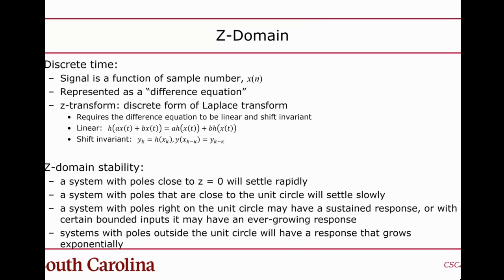The shift invariant and linear properties are just analogs really. Linear is linear, and this means the same thing as it does in continuous. But shift invariant versus time invariant just means that you can shift the time, and none of the coefficients in the system depend on the sample number, essentially. Now, the other thing that's a little frustrating about the Z domain, there's a couple things.